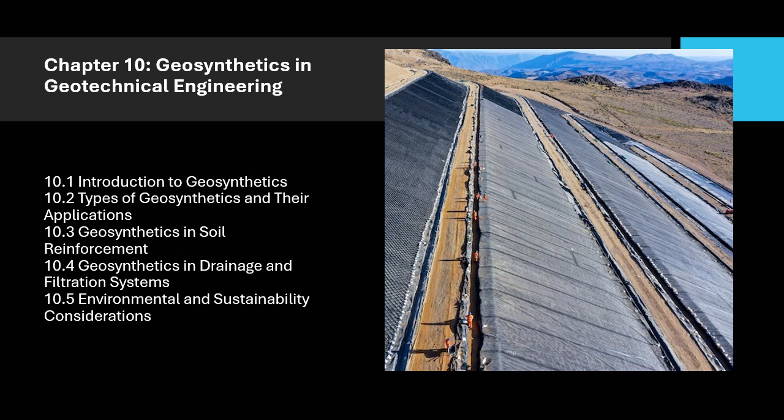3. Prevention of clogging. Geotextiles and drainage composites provide a permeable barrier that reduces the likelihood of clogging. They prevent the migration of fine soil particles while allowing water to flow through freely, ensuring that the drainage system remains effective over time.